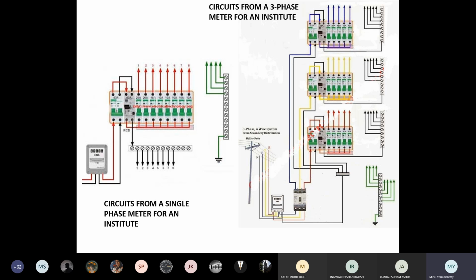So which is the start point? Where will the problem be? All the electrical load of this whole place will gather, and the first jolt point will be your MDB. So that will trip. So you know, okay, bedroom 1 is in a problem. Check its circuits. Okay?